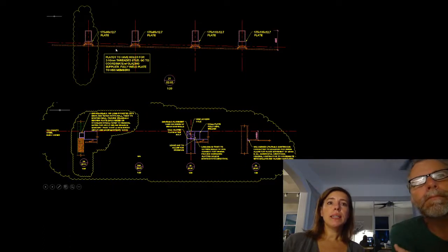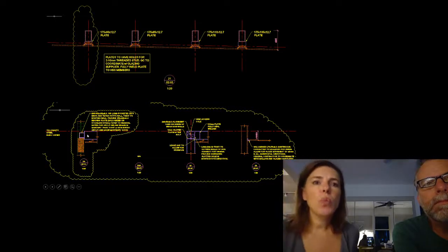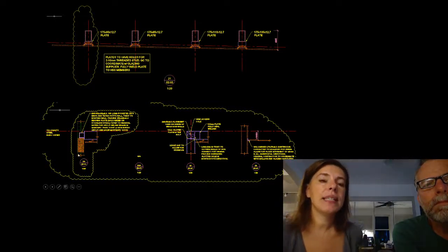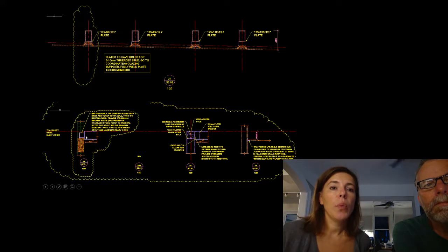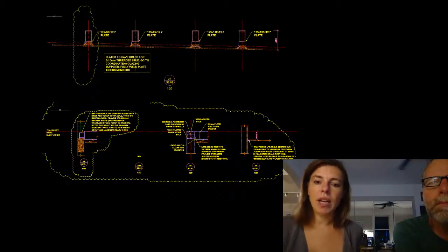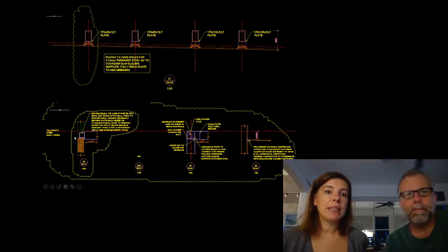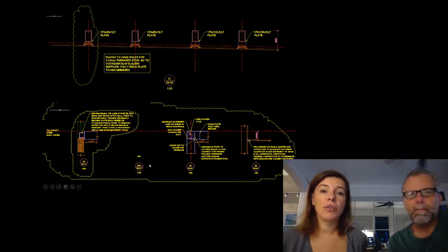So you can see here a cross-section through the canopy that was sloped to drain. We had these HSS beams running at the top that had spider clips down to the glass. These were some of our connections into the existing masonry, where we put these clean HSS bearing lintels that we could come in. We also needed to allow for tolerance for installation. You know, they're chipping out masonry to install this, and they want it to be perfect. So we had to build in something that allowed for tolerance in installation.